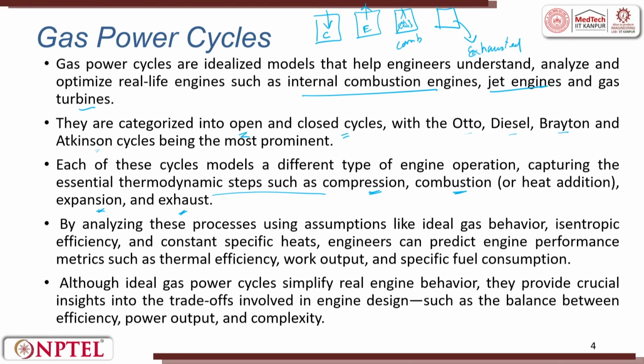When you talk about compression, expansion, you will try to have a PV diagram, you will try to have a TS diagram, straight. By analyzing these processes using assumptions like ideal gas behavior, isentropic, we have seen all these things, isentropic efficiency, constant specific heat, engineers can predict the engine performance metrics such as thermal efficiency.